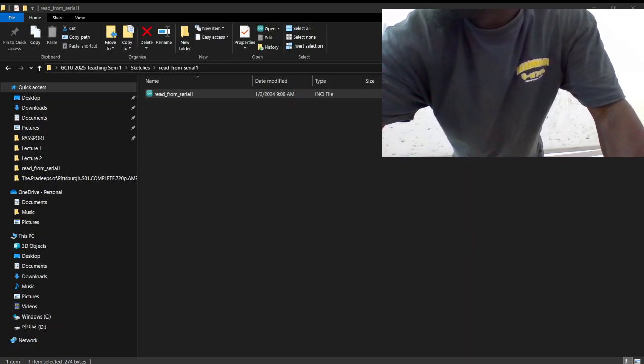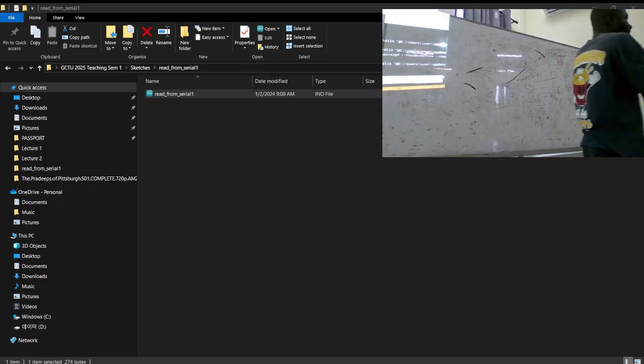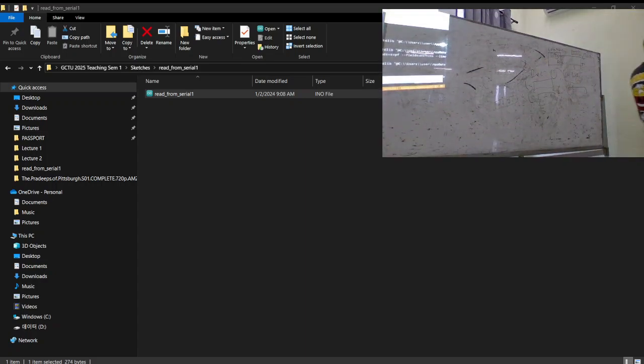So it will compile the code, give me how much RAM it will use, give me how much flash it will use, and once I check those values and see that it's about what the board has, then I'm in trouble. I'm going to really write my code to use smaller RAM and stuff like that. I've already done that.